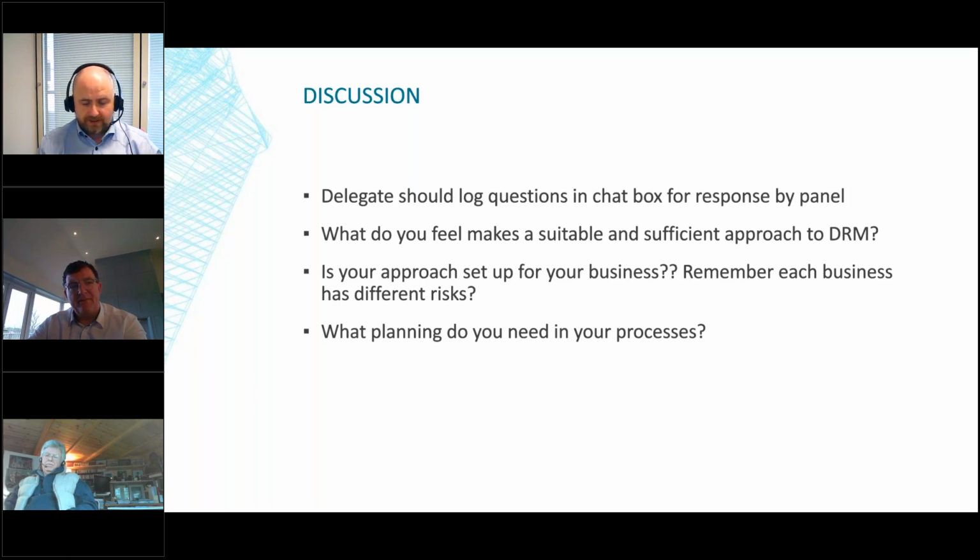Well, as Paul had said, I'm looking at this from a unique perspective, from a specialist subcontractor, and namely precast. So for me, it's really early engagement. So early engagement with the specialist subcontractor, because they have a very specific set of risks, and how those specific risks tie into the specific risks on site. Given an example, you could have a crane in the middle of a city centre, that if there's no communication between the precast manufacturer and designer and the contractor on site, that crane could maybe only take, say, 5 ton at the end of the jib.